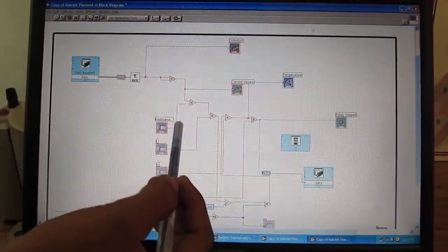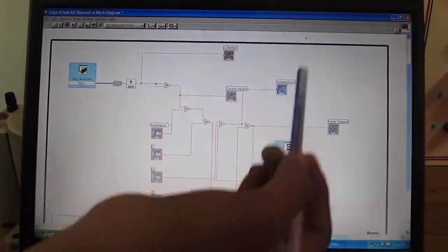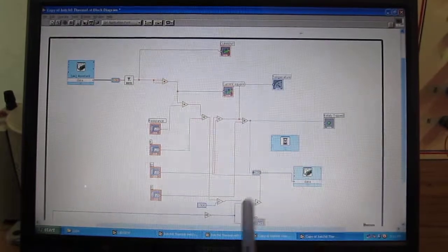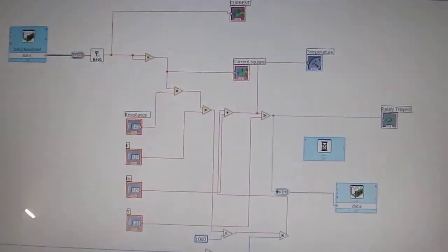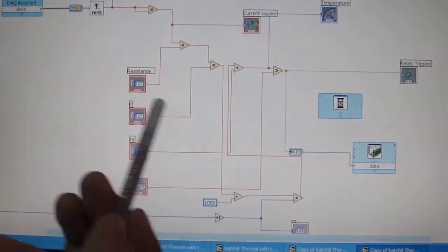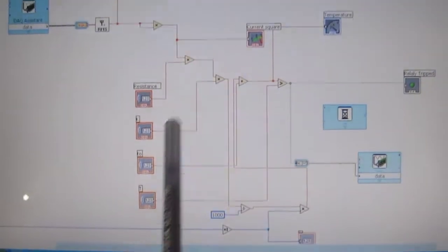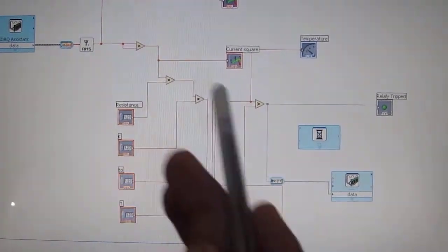That I square R component is in watts, so that is going to be multiplied by K. K is actually the machine temperature rise constant: as we gradually load the machine, how the temperature is going to rise. The slope of that curve is nothing but this K value. K units are degrees centigrade per kilowatt per second, because temperature is also a function of time.